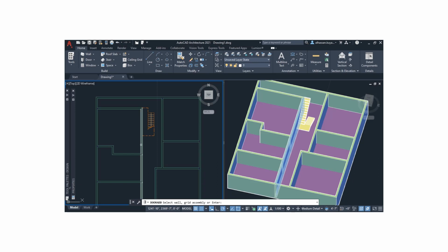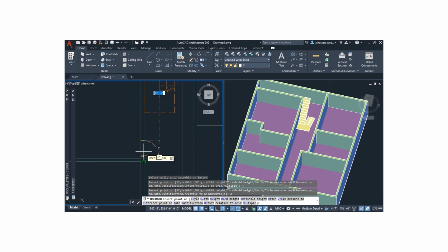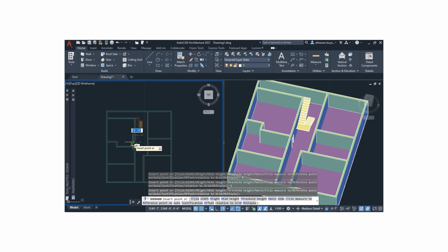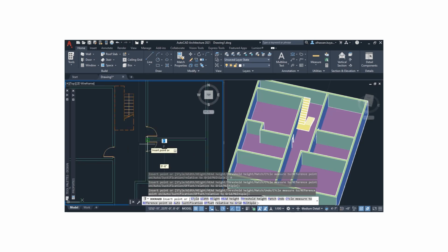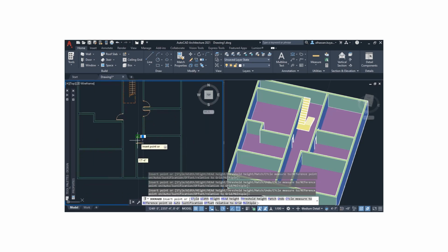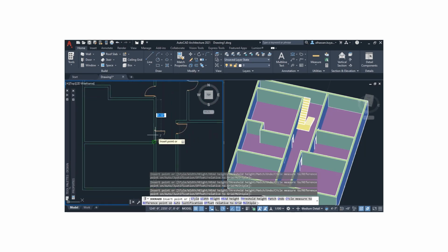So now when you want to position the door, you click on the wall where you want to position the door and the door will appear. We have a point here where we set it to auto so that it will position for us automatically. As we hover around the wall, you see the gestures we get. So we want to position it like so. So we click. That's for that room. Next, we want to position a door here also. So we click here. Here also, we click here.